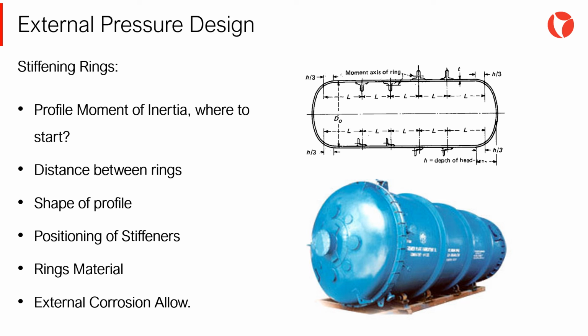Or, for example, the shape of the stiffener. If possible, standard profiles should be used. They are generally cheaper and the manufacturing process requires a lot less man-hours. And at last, the position of stiffeners is very important. Locating rings over circumferential weld seams shall be avoided when possible.